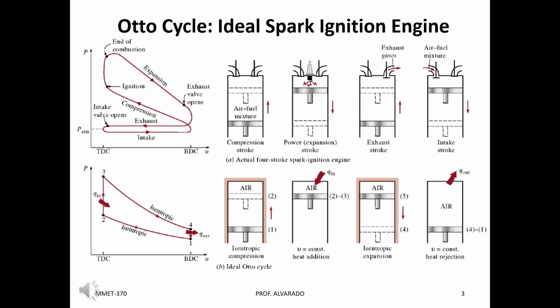Also on the slide you can see a comparison between the actual four-stroke versus the ideal four-stroke. The ideal four-stroke just considers air as the gas inside the cylinder, but in the actual engine we have an air and fuel mixture which makes the combustion happen.